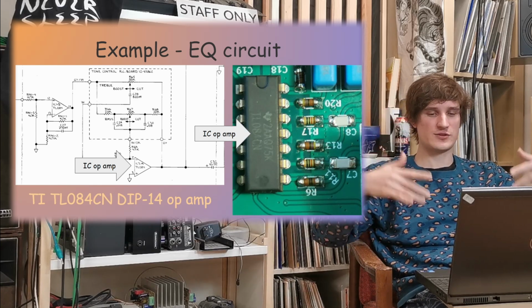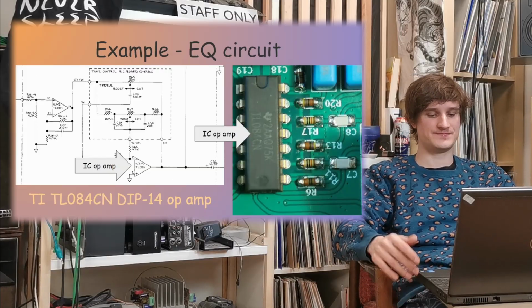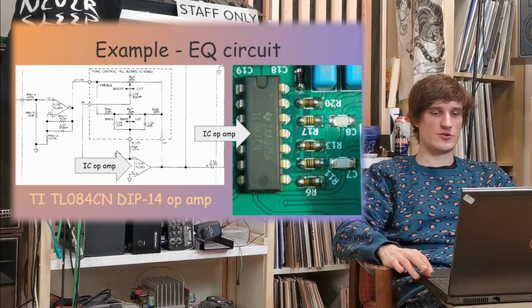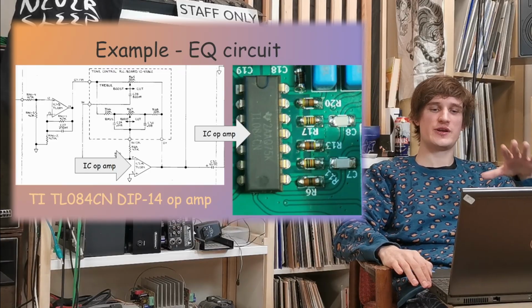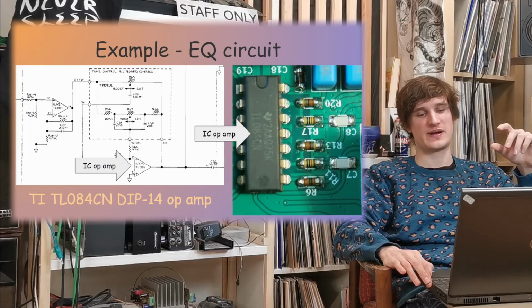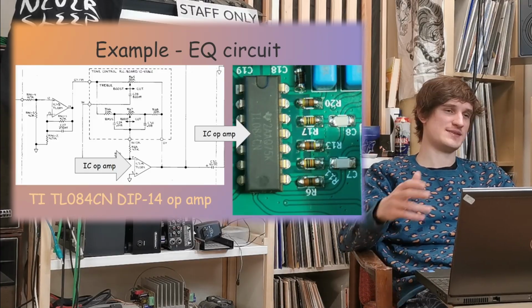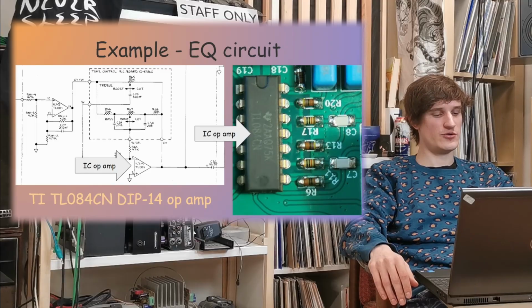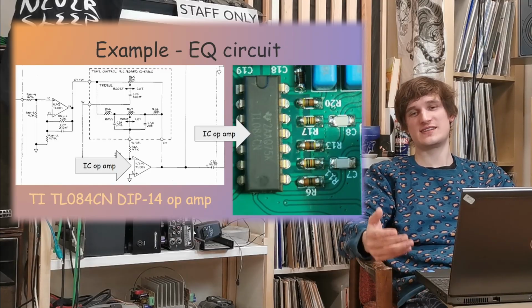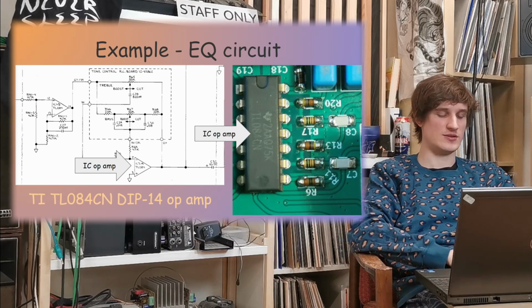It's not a super fast, high bandwidth circuit. So here I wouldn't worry much about parasitics, so I went with a larger package just to be faithful to the original. This is not a very scientific decision, but I wanted to stick to the original this way.